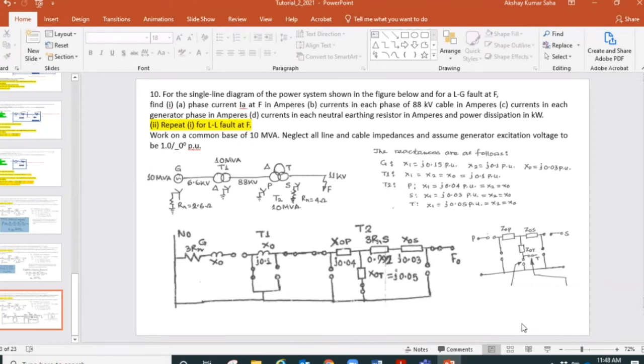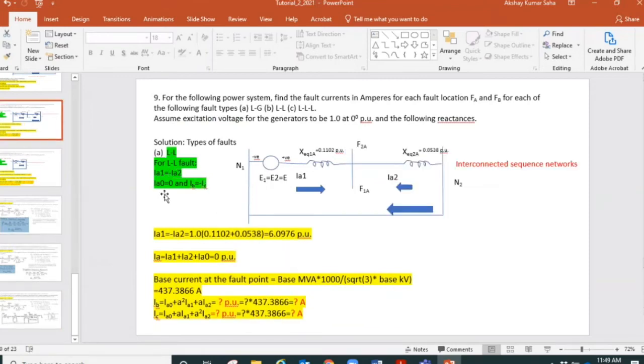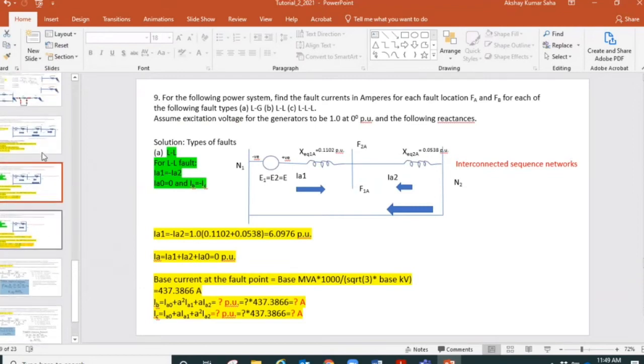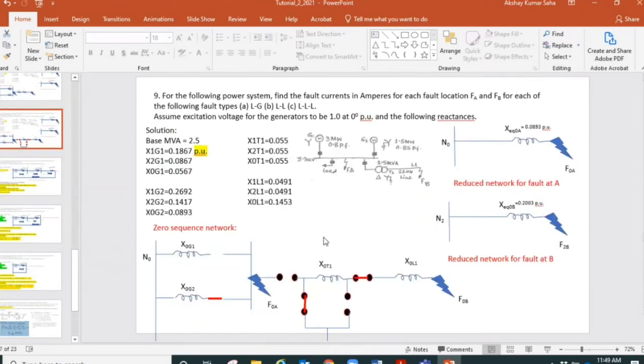So you said you intentionally left that switch open. No, intentionally I showed it connected for the generator, because if you remember, for the generators, what we were doing for the zero sequence network: when I was considering the zero sequence network, I was always showing an open and then I would close it looking at the connection.